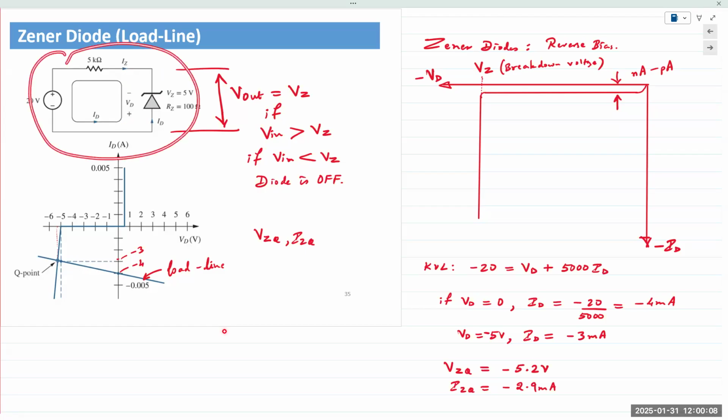As simple as the circuit is, you have one voltage source. There's only one source in there. So that voltage must be dropped across the resistor and must be dropped across that Zener diode. If we use the diode polarity and the diode current right there, KVL would not work. And that's the thing I wanted to point out before we do analysis on Monday. Okay, so it is opposite. VZ would be plus at the top, minus at the bottom, but diode voltage is negative.